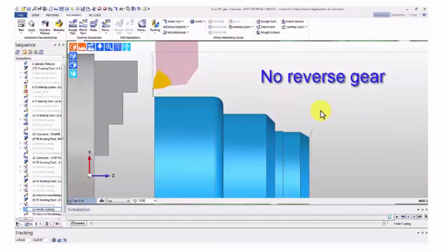So you want a sensible path, and my advice is to start it and end it. Don't go off somewhere else and start doing something else. Apply it. So in this case it would be G42 to apply and G40 to get rid. So you've got this nice simple path, completely isolated in and out. So you need to have this lead in and lead out. Okay, so that's rule number one.